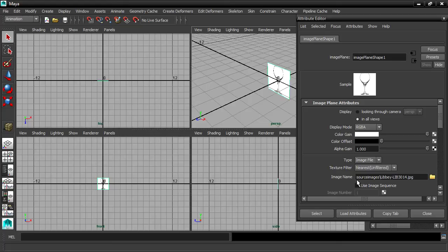If you see a drive letter or a volume name here, then that's a problem. You never want to see that in Maya or really in any 3D program. If you see a drive letter or a volume name, that means it's an absolute path. And your 3D program is going to go looking for that file in that specific location from now on forever into the future. And if you need to move that file or change the name of the path or do any changes really at all, then the path is going to get broken and the file will not be found. You'll get an error message and you'll be sad. And you'll have to then take extreme measures in order to fix the problem.